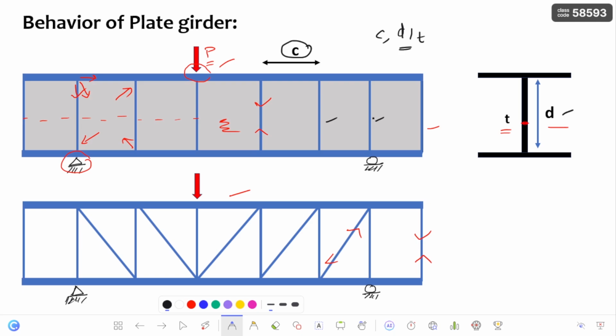And coming to the shear capacity of the web, it is the sum of the strength before onset of buckling and the strength after post buckling of the web. I already discussed the onset buckling and post buckling. Initially the web buckles, and after that strength is generated due to the tension field action, and this tension field action is due to the panel strength. That is, after providing these transverse stiffeners, the panel acts as a unit, and in this unit tension field action is generated.